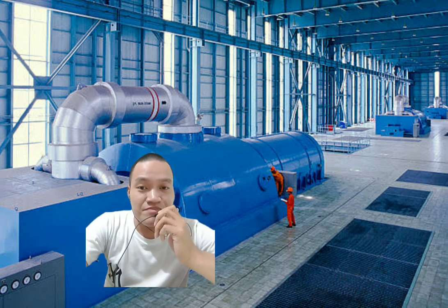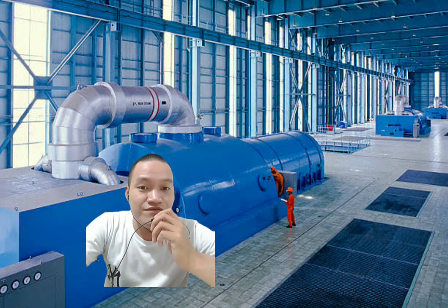Start the main circulating pump for the main condenser, then start the condensate extraction pump with the air ejector recirculation valve wide open. Next, open the maneuvering valve bypass or warming through valve if fitted. This allows a small amount of steam to pass unheated. This should be continued until the temperature reaches 75 degrees Celsius at the LP turbine inlet after 1 hour. Freedom of movement should be checked.